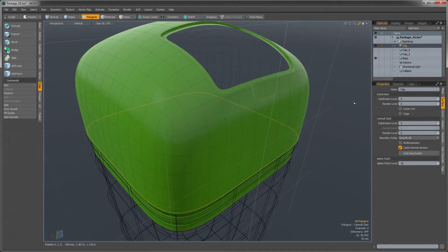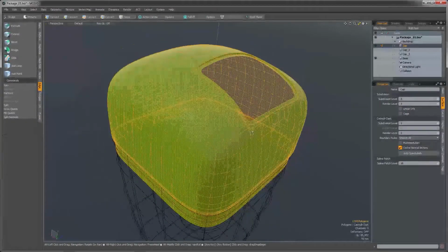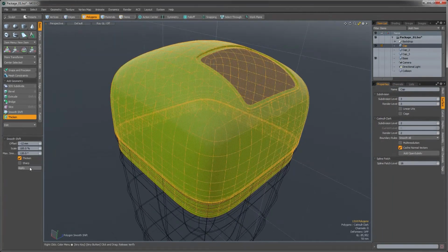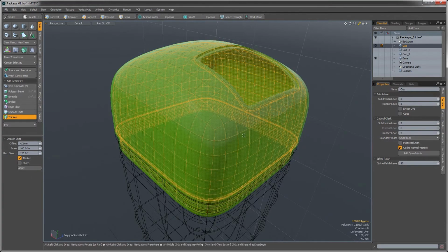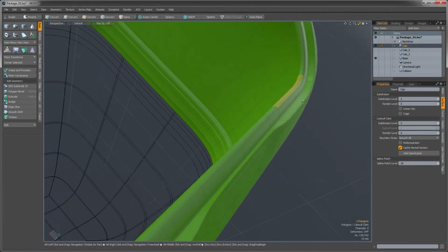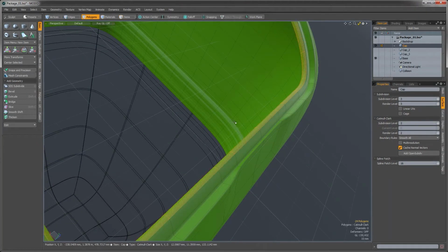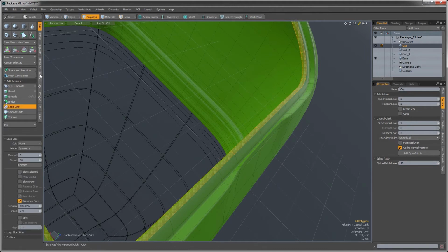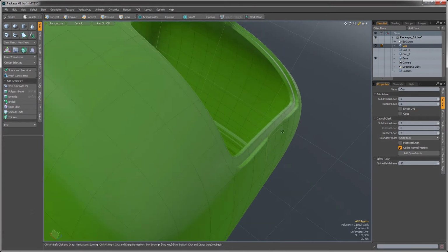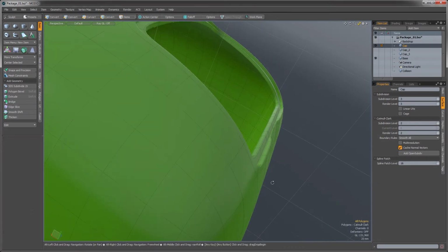So going into polygons mode, want to select all of our object, and then we're going to go into that thicken tool here, and that's -12, we want it to match what we did before, so I'm just going to click apply on that. And then I want to tighten up this edge right here. So loop again, and Alt-C, and we want 2, symmetry, and then something again under 5%. So something like that. Gives us a nice sort of believable detail.